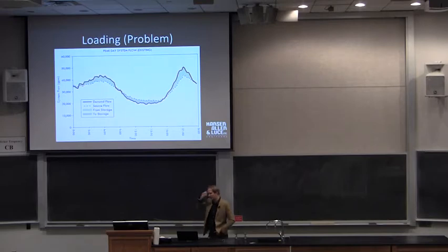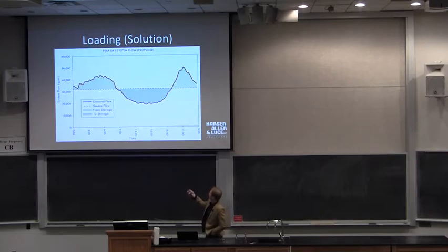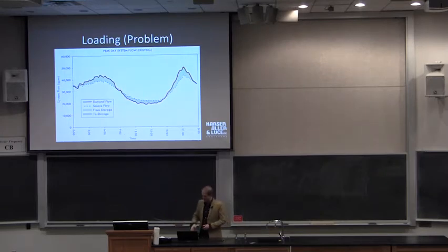So this is a real system, and this is what they did before optimization, where they would ramp up their pumps to meet that peak and not take advantage of their battery. So after talking to them, we got them to use their sources more consistently. And the difference between the dashed line and the solid line is the storage. So in this area is where the storage is being used. This is where the storage is being filled back up and used again. So there's a lot of volume or area between the curves. And as you can see before, there was very little usage of that storage.